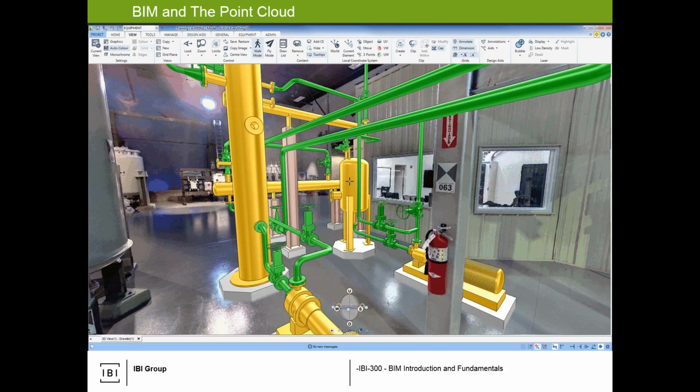And with this true 3D dimensional space, you can actually assign intelligence to collections of points. So that column with the fire extinguisher, I can actually say the 1 million points that make up the column, we'll call that a column. The 1 million points that make up the tank on the left, it'll get assigned its name. So it starts to actually take points that are forming content and apply intelligence to them so that they can be harnessed throughout the project. And then design within. When you cut your drawings, plan, section, elevation, etc., the point scan can be the backdrop or not. It doesn't matter. It's at your choice. So very powerful to quickly BIM my existing without spending hours and hours and days trying to do it.